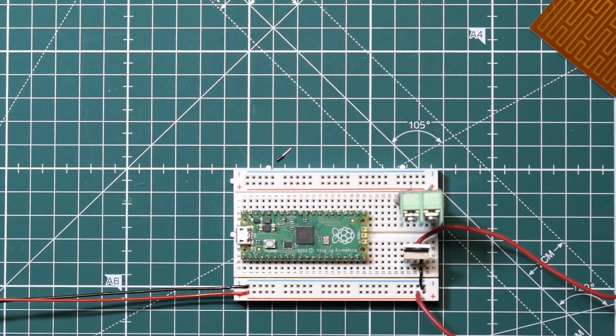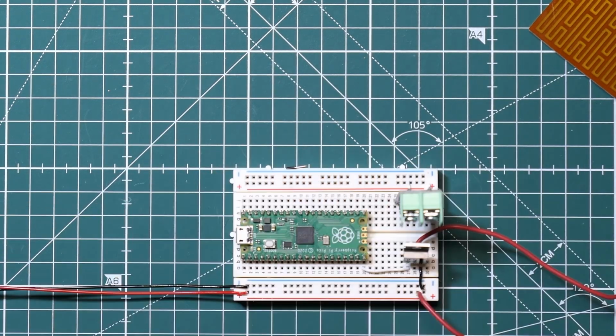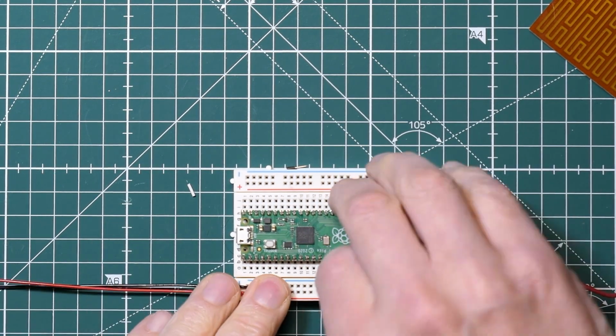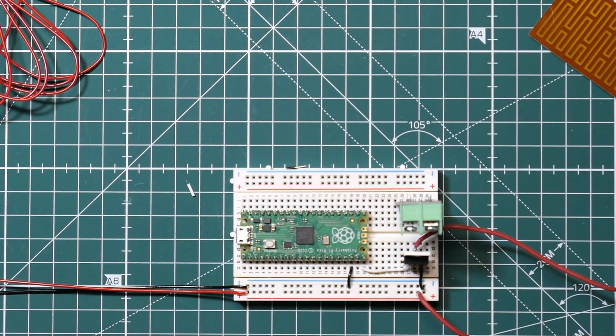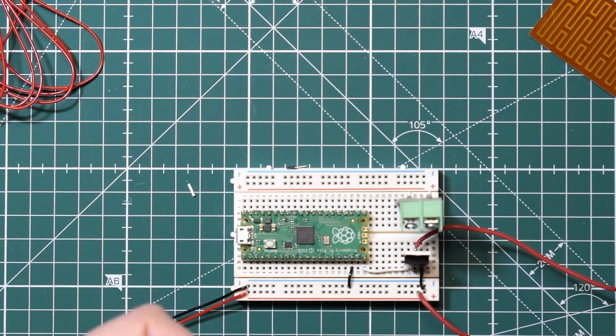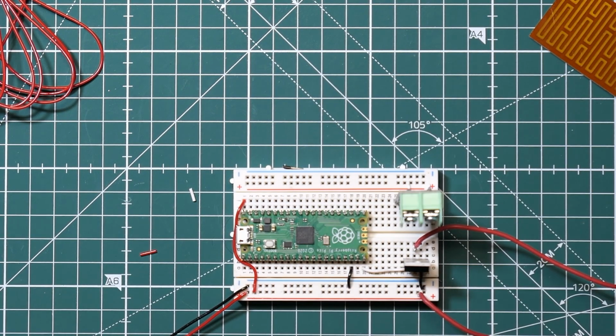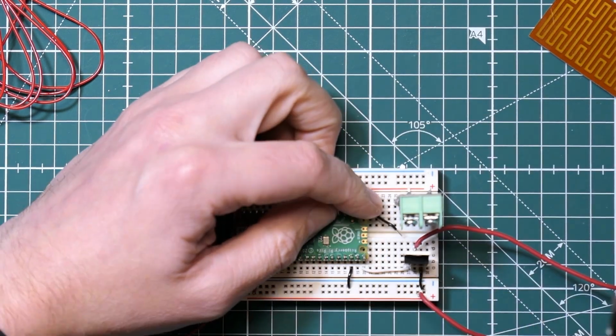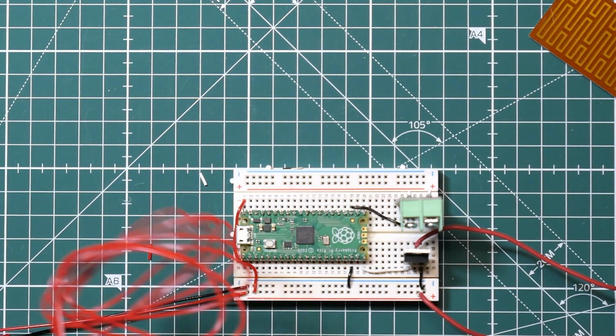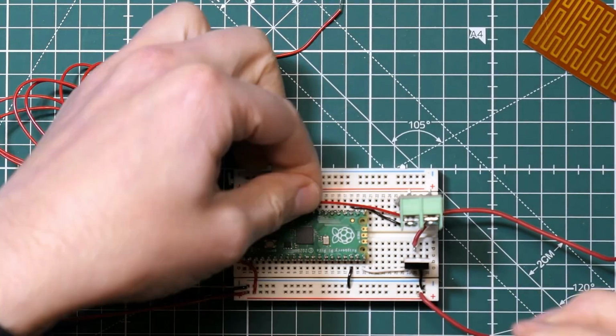The gate of the MOSFET goes to the Pi Pico, so it's the Pi Pico that determines whether the gate's high or low, and that's connecting to pin 19 on the Pi Pico, which is actually GPIO 14 or GP14 in Pi Pico terminology. I connect the thermocouple amplifier as well to just several of the GP lines and set them up correctly in the code, and that's really it.